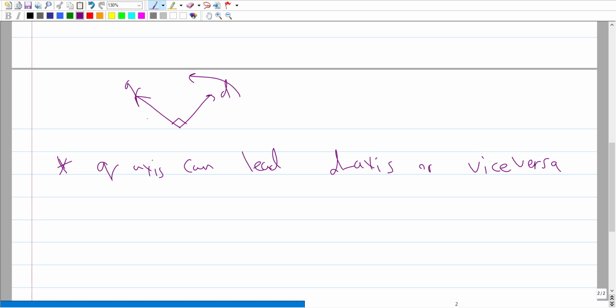But some of the old references, such as the book by Professor Anderson and Ford, or the book by Professor Bergen, consider the q-axis lagging the d-axis by 90 degrees in space. So this is another reason that you can encounter different transformation matrices and different formulas.